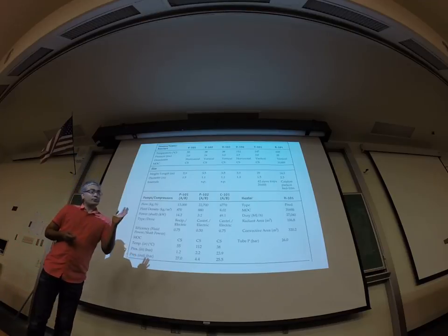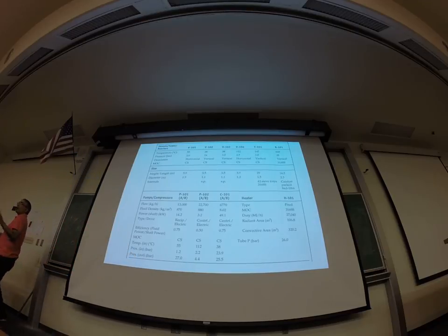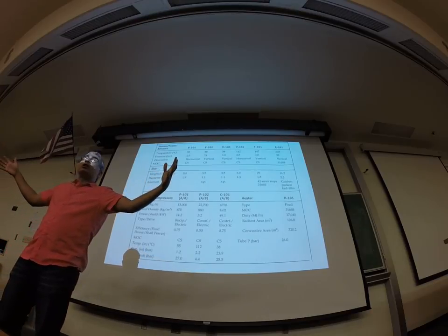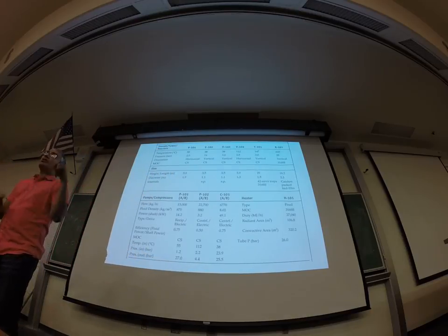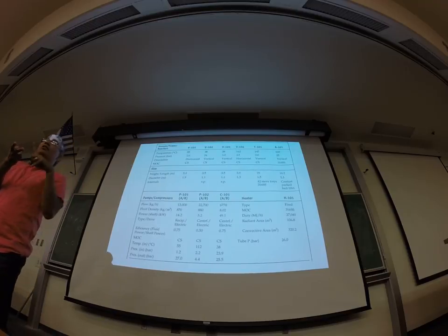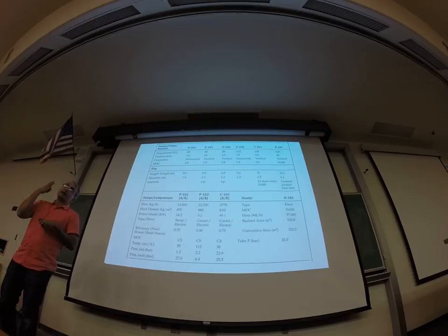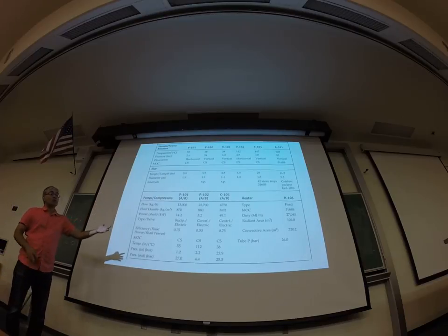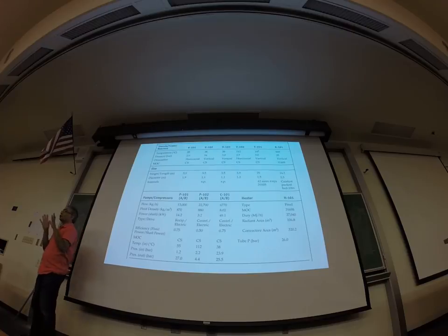All right, so you can see that essentially what you have for a PFD is an actual process topology, which tells you all the connections. Then you have a table for all the streams, and then you have a table for all the equipment. So those are the only three things that every PFD has. In some PFDs, some of this information may be on the PFD itself, but usually you have separate tables.